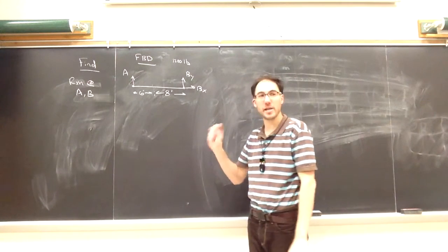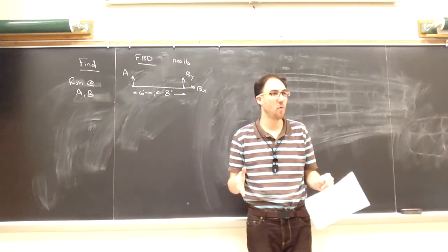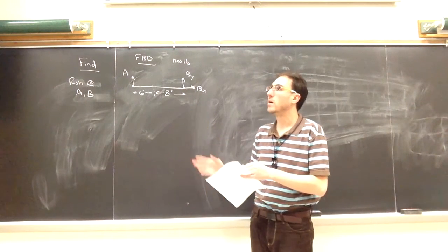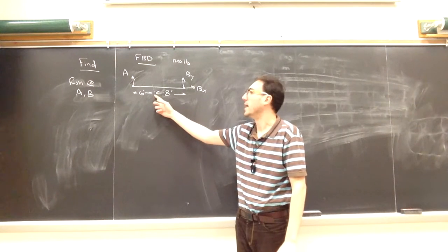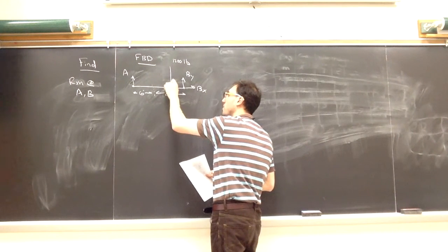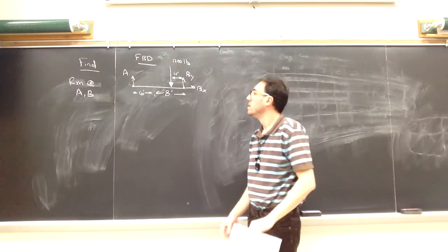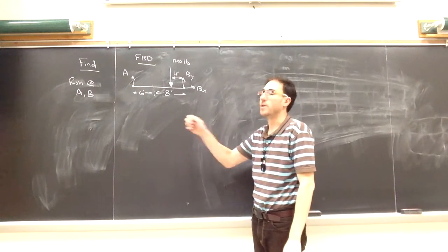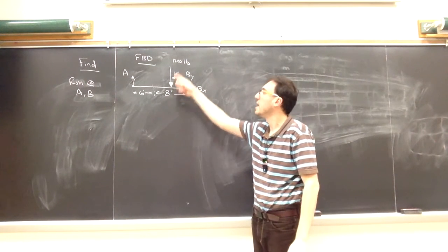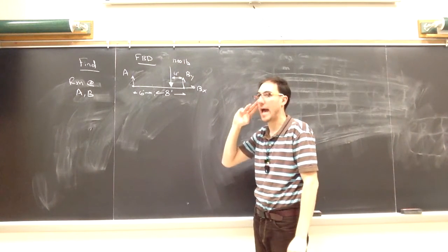The first thing is, how much is it? And then we have to see where to place it. Because it's a rectangle, like we saw before, its placement will be at half of its base. So it's 4 feet from B, which is also 4 feet from this line where that triangular region ends. So it's a 1,200 pound force located 4 feet from B. That's the equivalent point load. If we took that entire distributed load and placed it at one location, that's where we can put it, and that's how much it should be. That's equivalent externally to that distributed load.